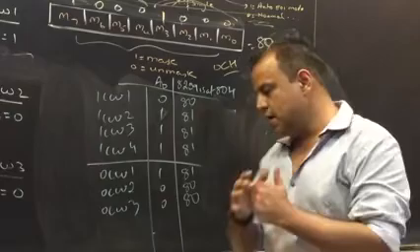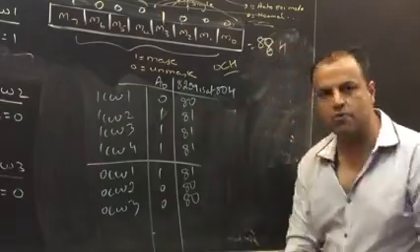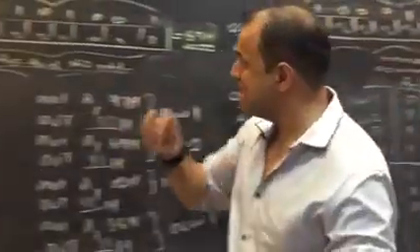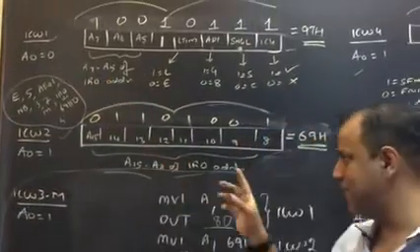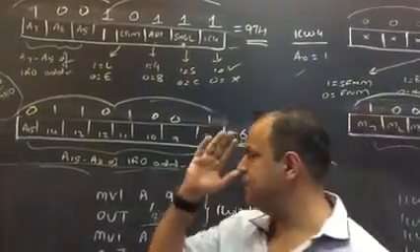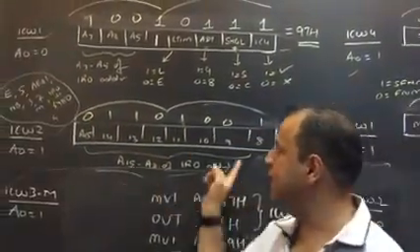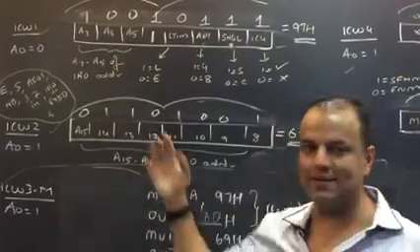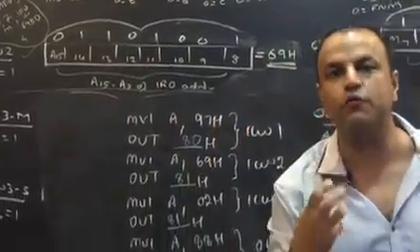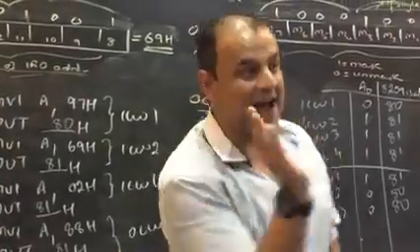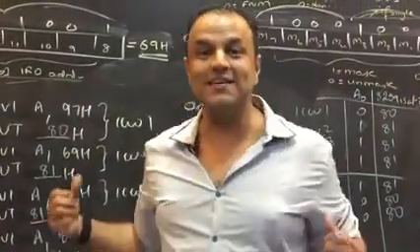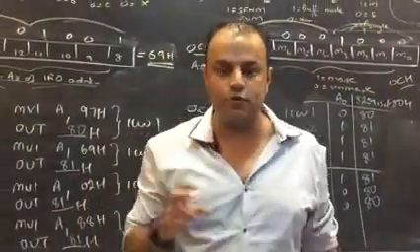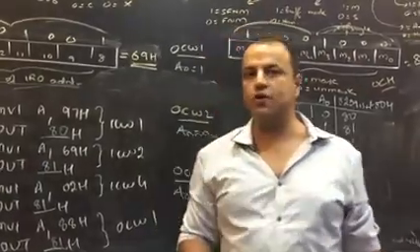First of all, are you clear? Please, for God's sake, don't mix this with A7, A6, A5. Please, I say for the nth time, those were A7, A6, A5 of the ISR address. Of whose address? ISR address. ISRs are stored in memory. This is the address of 8259. 8259 is an IO device. Please do not get confused.